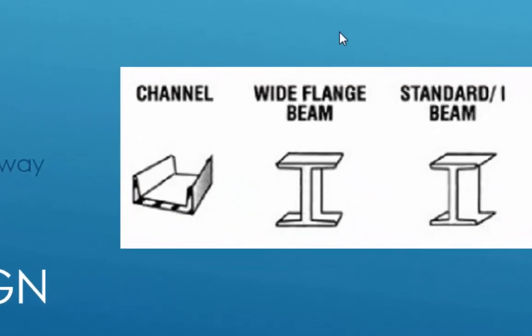And so in certain situations, it might be very good to use these, and they might have other advantages, such as being able to be easily sourced or have great connection points. Because you can imagine that putting other beams and joists in here, if this is in a column, is a lot easier to do than if you had a round pipe. So that may very well be excellent reasons to use a wide flange shape.